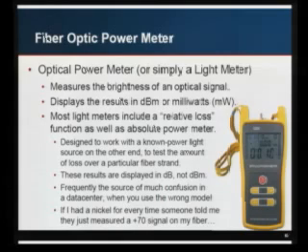And I've had a horrible experience with data center techs where no one knows how to do this correctly. If I had a nickel for every time someone told me they just measured some signal that should be blinding them, I'd be very rich. So when you work with light meters, really keep that in mind. Make sure you're looking at the right mode. But basically, these are a couple $100 devices. So if you do any work with fiber, get one. Get one on eBay. Get one new. Doesn't matter. They're not that expensive, and they're really essential to doing any kind of troubleshooting.